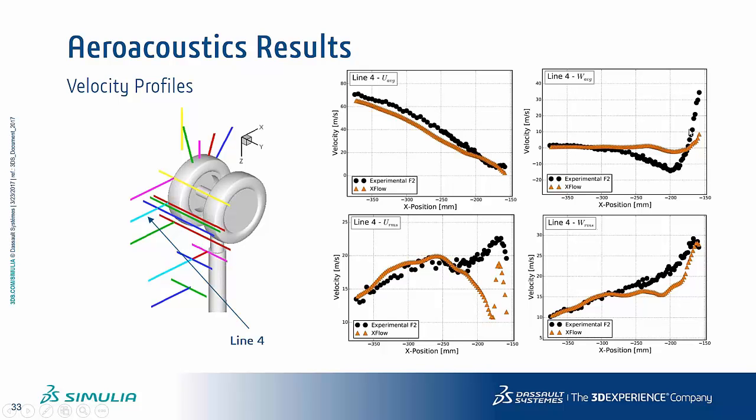We don't get that much of decrease here, but in general the trend then goes up again as expected. And then the fluctuations also are about the right amount here. We speak about 15 meters per second of root mean square value of velocity, so that means fluctuations are pretty okay. Bit more deviation again, like in this area, and here the fluctuations are also good in that line.